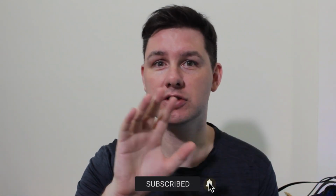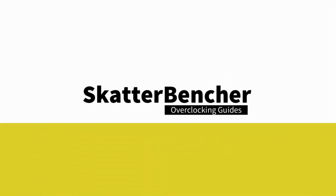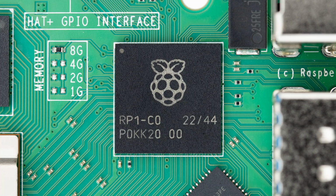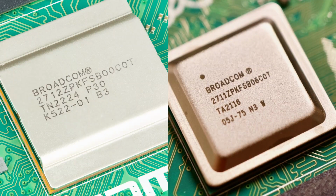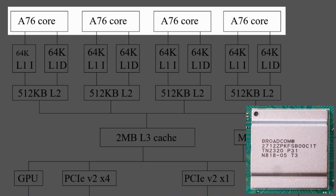But before we get into the overclocking, let's first have a look at the hardware and the software that we'll be using in this guide. The Raspberry Pi 5 is a single board computer featuring a Broadcom BCM2712 SoC and an RP1 Southbridge chip for I/O connectivity. The BCM2712 is a 16nm SoC succeeding the BCM2711 of the Raspberry Pi 4. It is built around a quad-core ARM Cortex-A76.